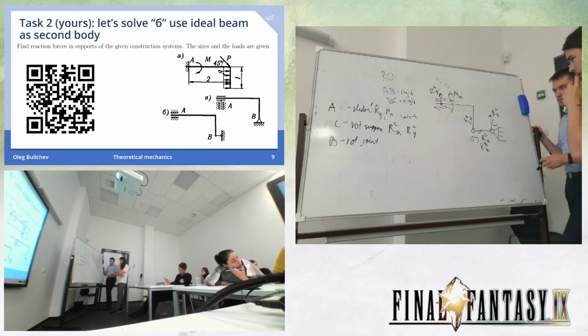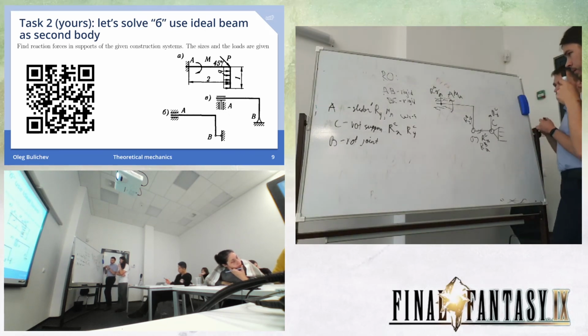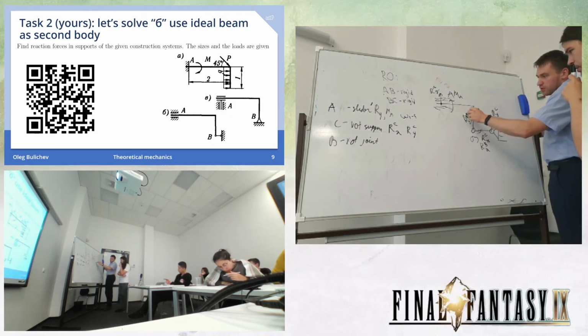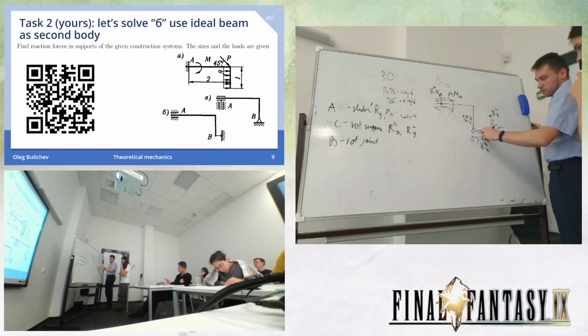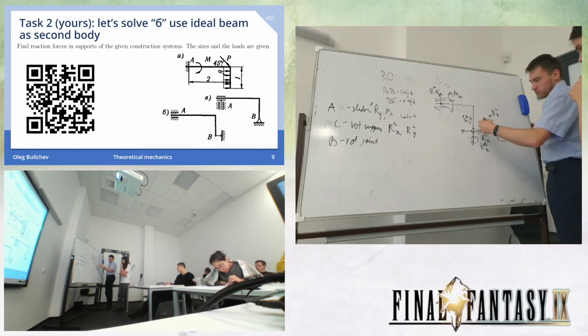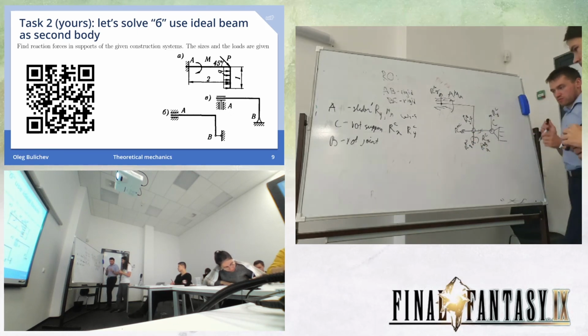For example, we disregard this part. In this case you can see, look at AB. AB can move this way. So we have this B X. We just don't know, because we can move freely like this. The reaction force should be zero, as we can move freely in X. So the direction that we move freely in doesn't have any reaction.